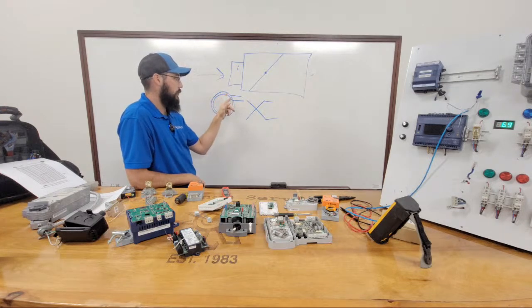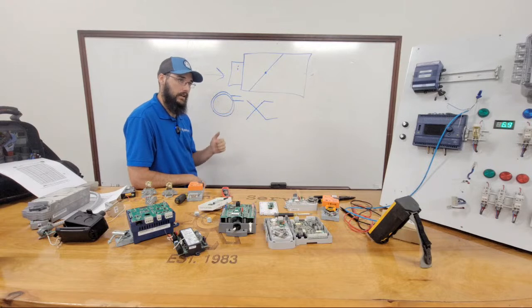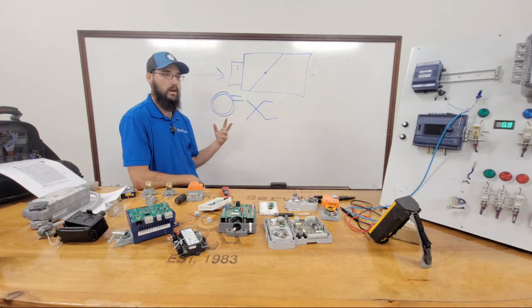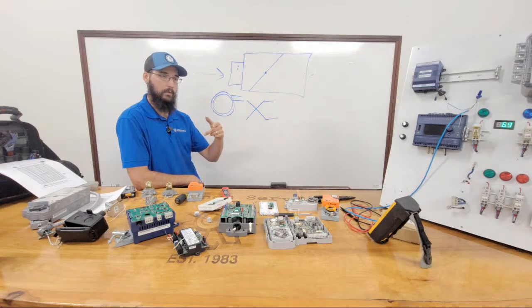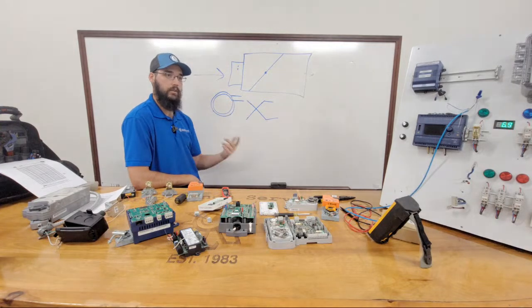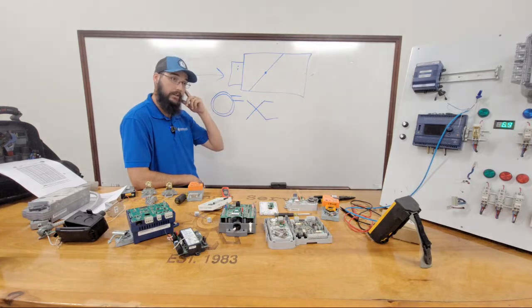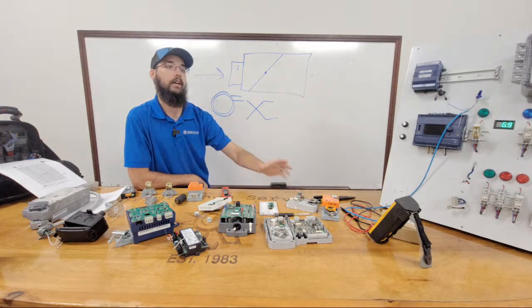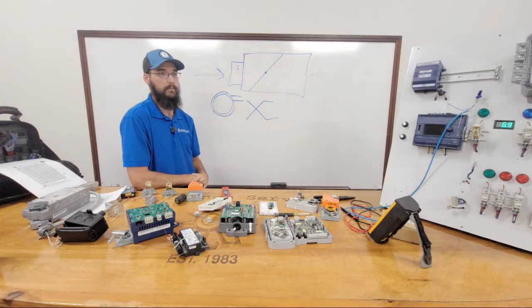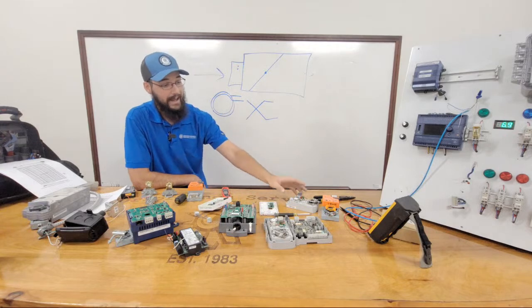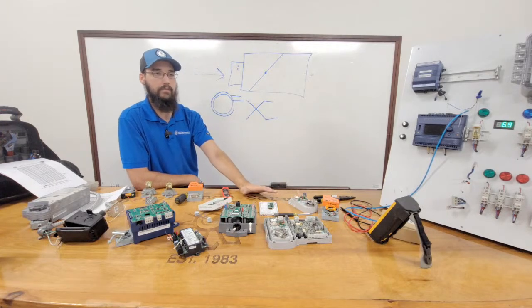So if these don't pick up properly, they could get clogged. These sensors could just fail. Those are probably the two most common things. Either the sensor pickups just go bad, or the rings themselves get full of dust and clog up. Then they're not going to read CFM properly. So that could be affecting why the actuator is not adjusting properly, depending on how they've got it configured and everything else. So you have to pay attention to these tubes and hookups, and I cannot tell you how often I find them backwards.